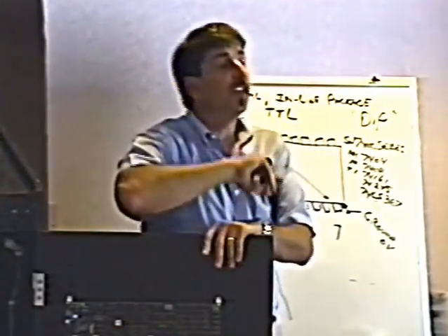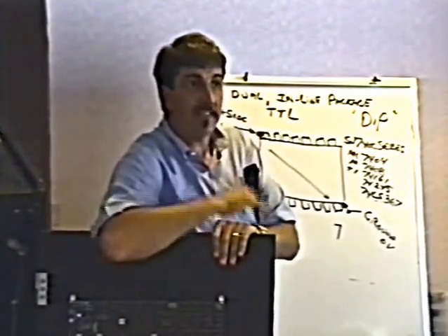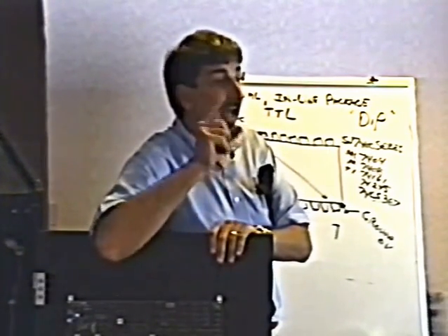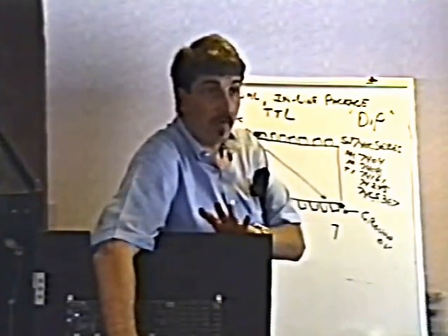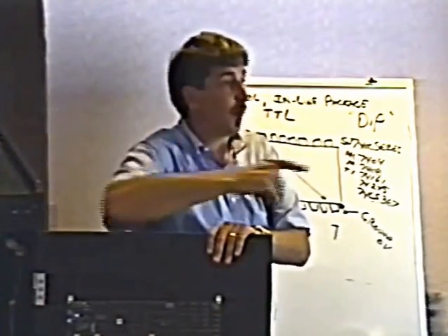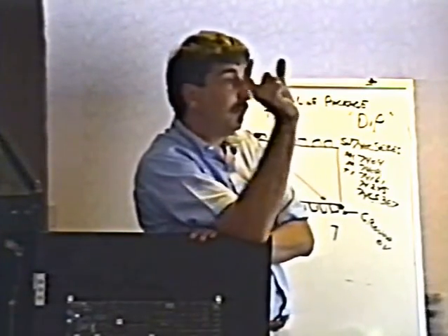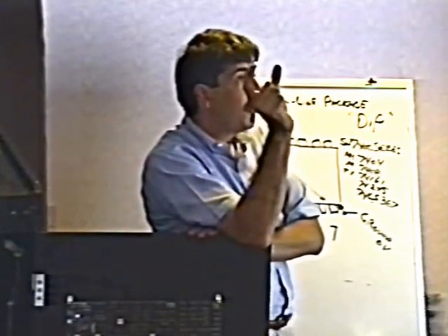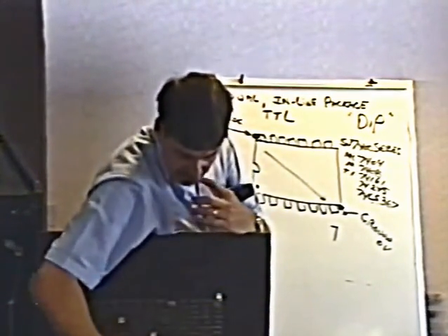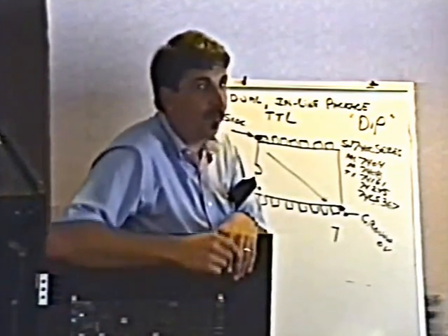You should always do this. Try the suspected bad parts in your good working test bed. The reason you do this is that you may have more than one bad integrated circuit on your bad board. This way, when you move it over, you can tell, oh, I moved this chip over, now the problem's in my new working game. Obviously, that chip that I moved over is bad. So you don't have to know anything about electronics to do that, do you? You just have to start swapping the chips. Make sure you swap the correct one. You know, have the exact same board, swap them one for one.